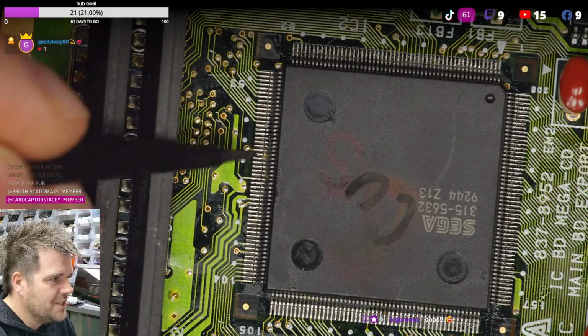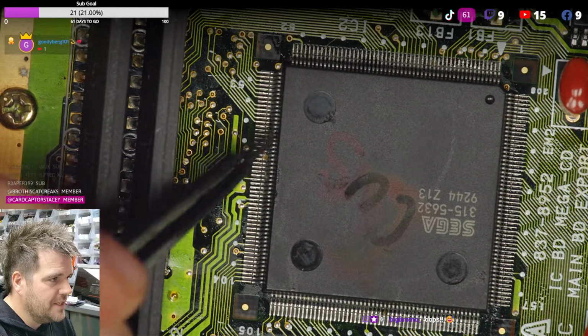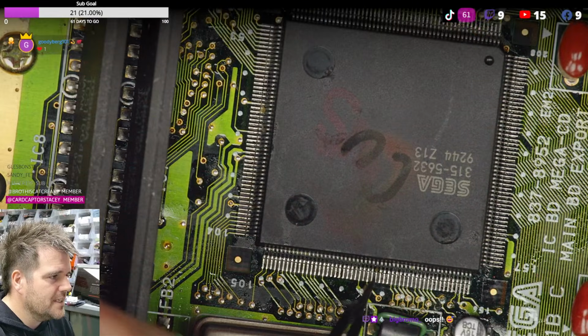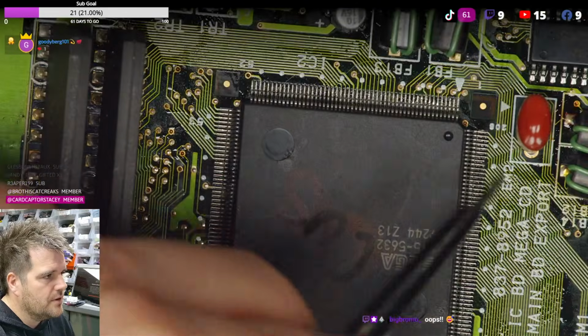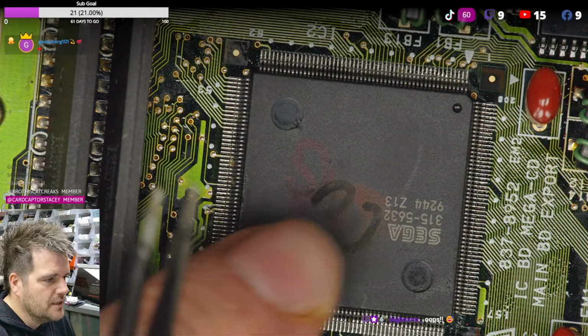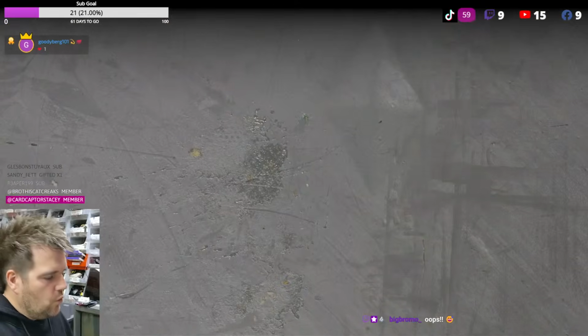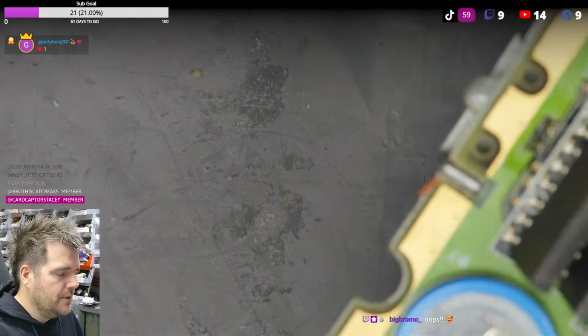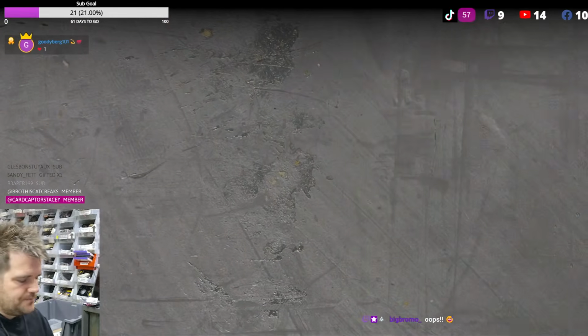These pins on the Mega CD Engine, these are even worse than the Game Gear. These bend so easily. So on these, I tend to lift them off, flow solder on the pins, hot air them back down, basically. So yeah, just a warning for drag soldering. You'll find out when you do it once, and then you won't make the mistake again.